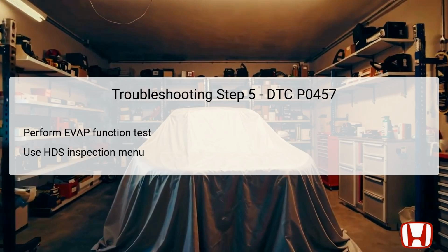If the test results indicate that the system operates correctly, it assumes that the issue may be due to poor connections or loose terminals at various relevant components, like the FTP sensor or the ECM-PCM. Conversely, if the results are not satisfactory, it signals a more severe failure within the system that must be explored during subsequent troubleshooting.